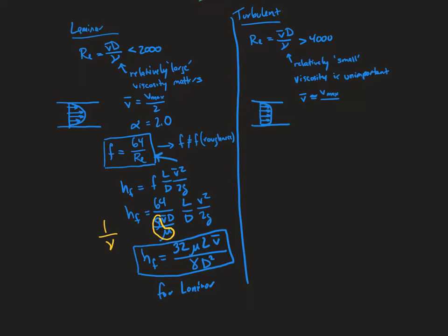They're basically equal, and that's why we say that alpha equals 1.05, which is approximately equal to 1. And that's why we always do that. So in this case, HF, the friction factor F is a function of the roughness.